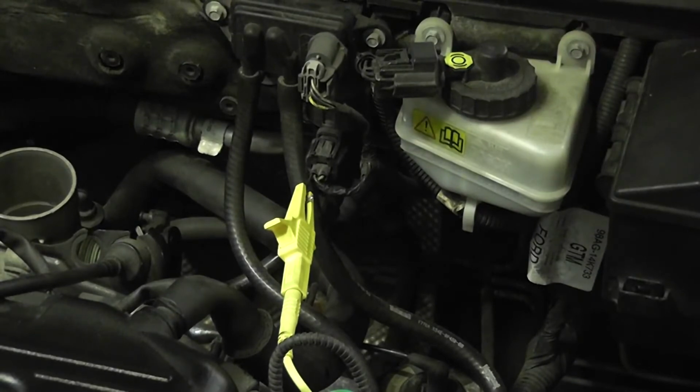There is no short to ground in the control wire. There is no shorted driver. That leaves us with one option, guys, and that is an open in the solenoid coil. So this trouble code, let's think about the code for a second. How's the computer setting this code? We have an EVR solenoid code.